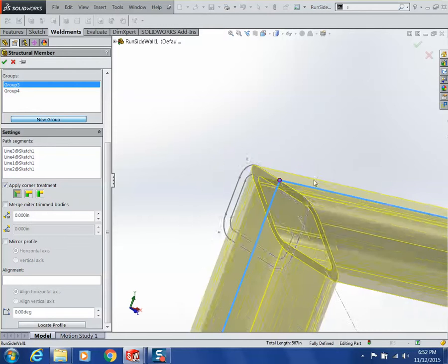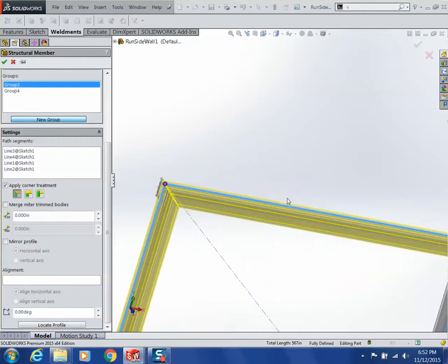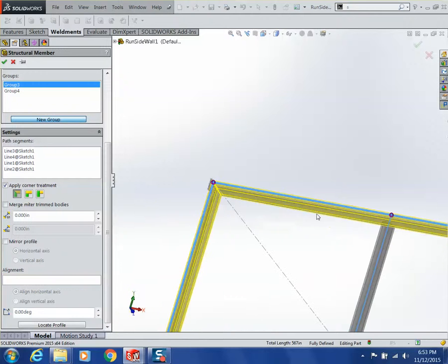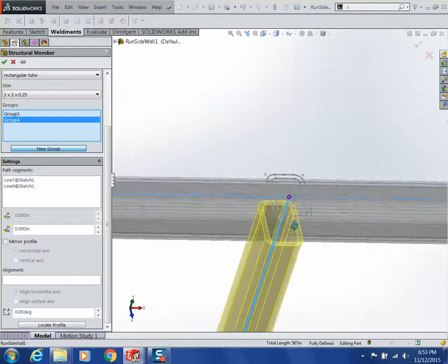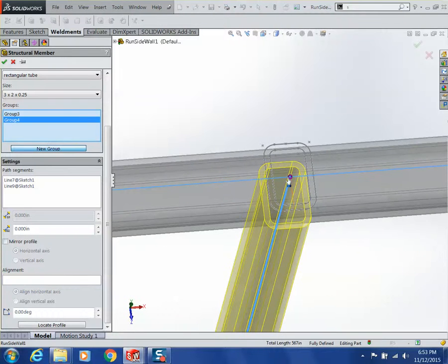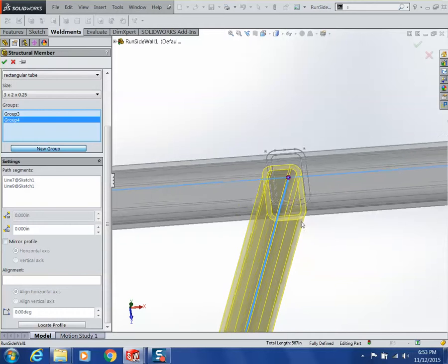So now as soon as I pick that, it snaps everything to the inside. So now that sketch that I had, which when I drew it, my intent was that sketch is the outside maximum size of my frame. Now as I drive that sketch to be whatever size it needs to be, my frame will be on outside edges that size, right? Because of the way the grouping works, if we go back and look, this second group didn't change as far as where that sketch was located. It still runs right down on center, which is the way I wanted it to be.